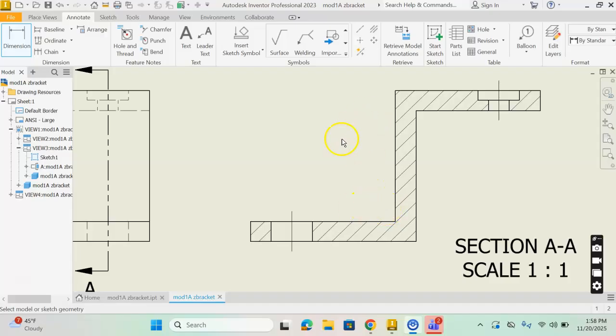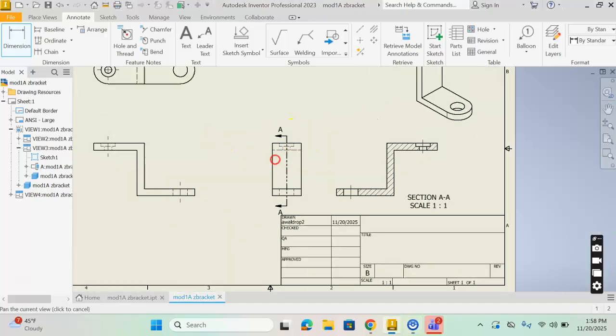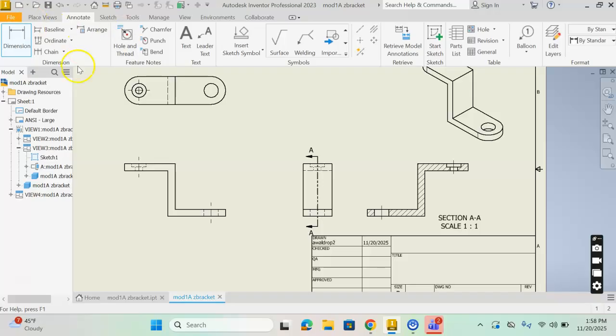Now, just like we can add center lines, we can also add dimensions and notes. We're going to also use the Annotate menu to do that. So for dimension, we're just going to go ahead and choose dimension. And let's say that I want to put a radius, but I got to go back and put my center mark on here. And we'll go ahead and add a dimension on here for this particular hole.